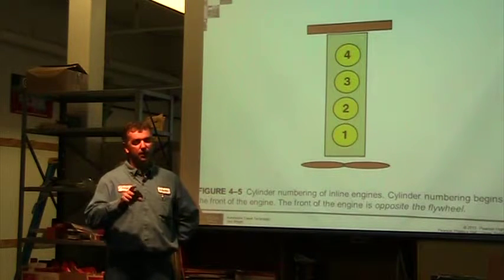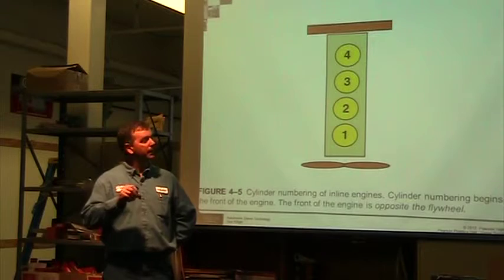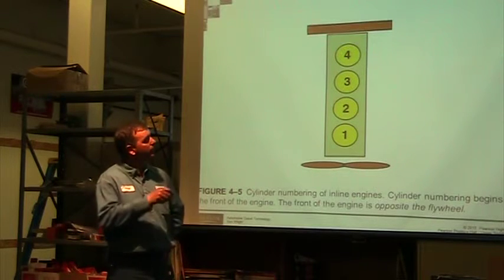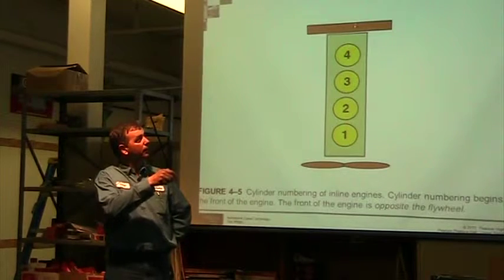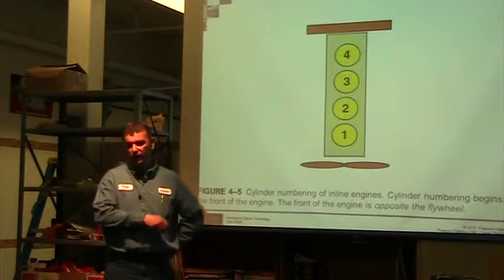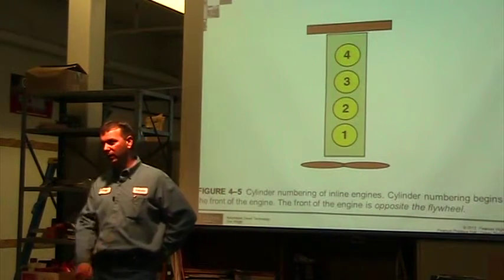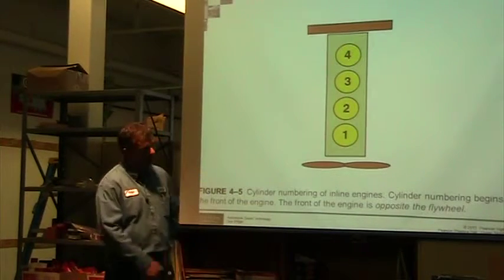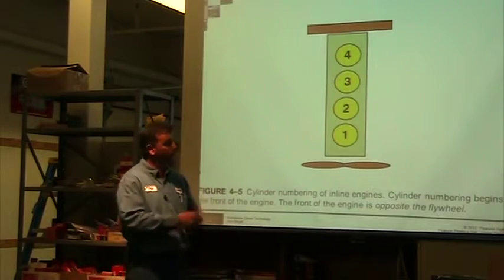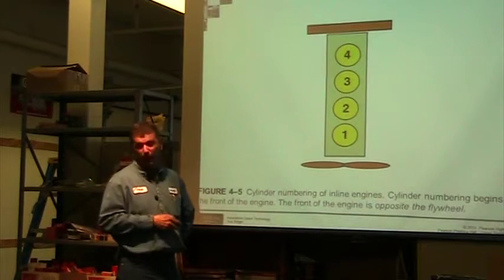And there is another brand besides GMR that also reverses the order. One is near the flywheel and whatever the last cylinder is, is towards the fan. So make sure you do not assume that the order's wrong. The order is the other way. That's a bad assumption.